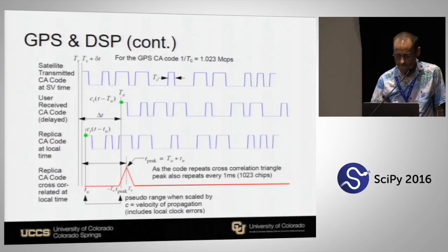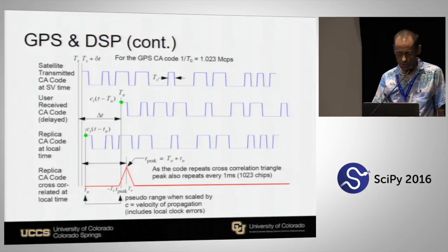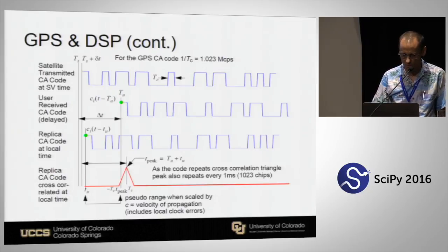So that's the job of the acquisition and tracking receiver, and that's the stuff that I've implemented. So I have to slide a local code along in steps, and then when it gets to a correlation peak, then it starts tracking it. And it does that across as many channels as I want to instantiate, and that's where I took advantage of the object-oriented nature of Python.